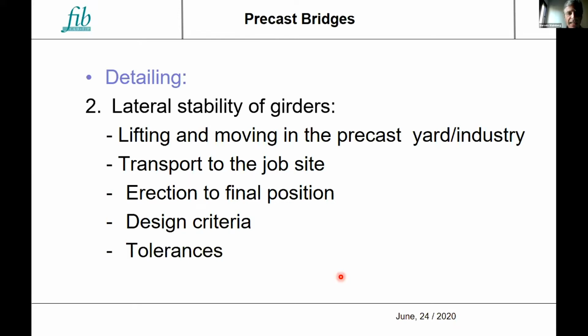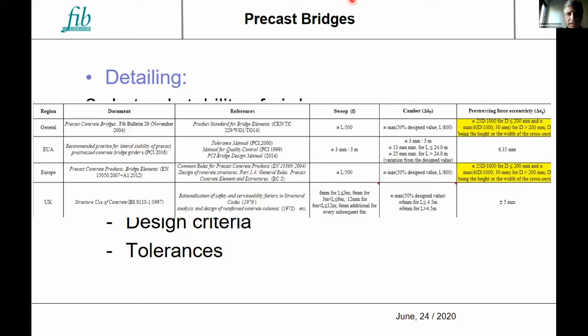And you will find, like in this table here, we take into account tolerances for sweep, for camber, eccentricity of pre-stressing forces, or eccentricity of strands or tendons.